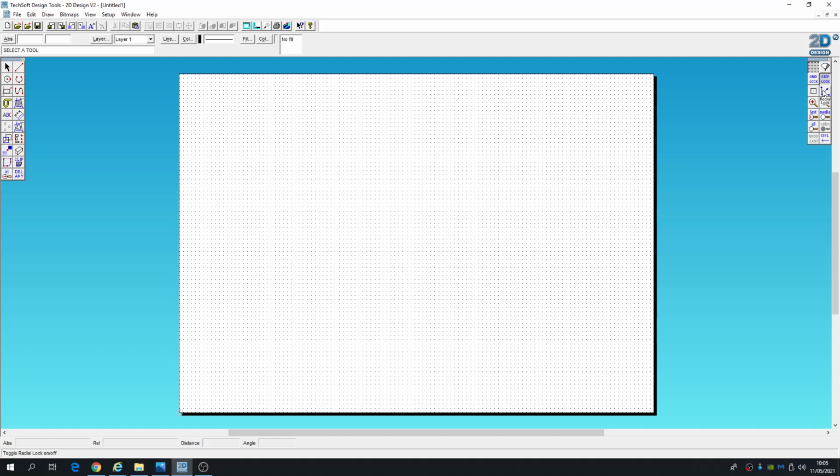And you'll notice what you've got here is you've got grid lock and step lock. Step lock means you can move your drawing whatever you've set it at. I set it at 0.5 millimeters. So if I were to, for example, draw an oblong, I can now use the select tool, grab that, and I can move that now 0.5 millimeter at a time till I get it lined up exactly where I want it, as in that.